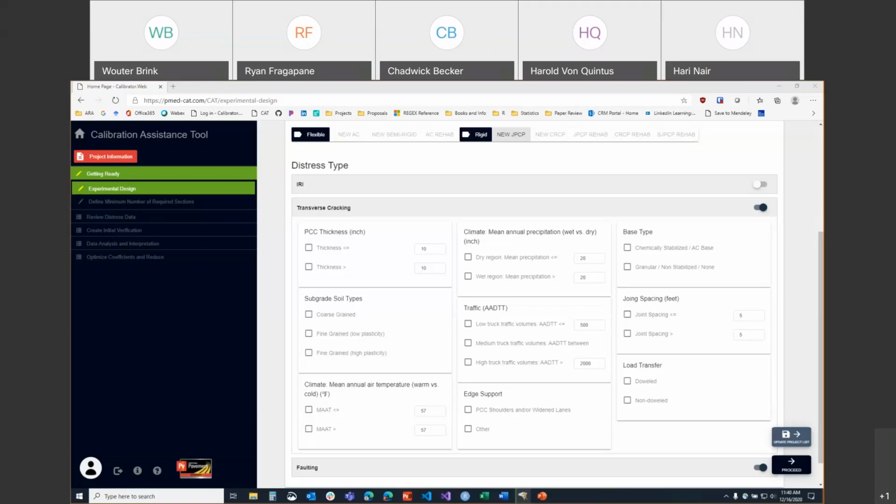Because they're both included, regardless, and if you've calibrated for bottom-up, the program is predicting top-down, and that is still being used in the IRI. So after you've calibrated top-down, you're going to have the predictions, and I would just do a validation. If there's a significant difference in the IRI, a statistical difference, then you should recalibrate. If there's no statistical difference, then I wouldn't recalibrate.